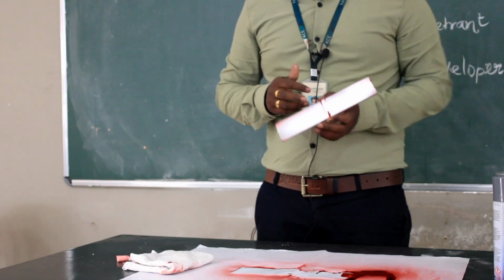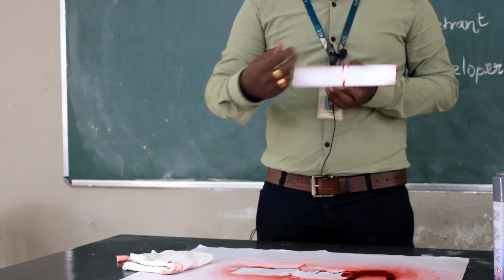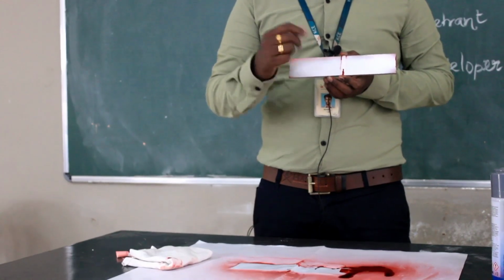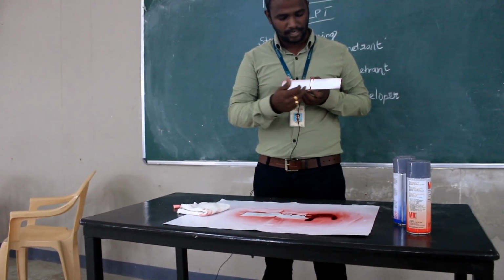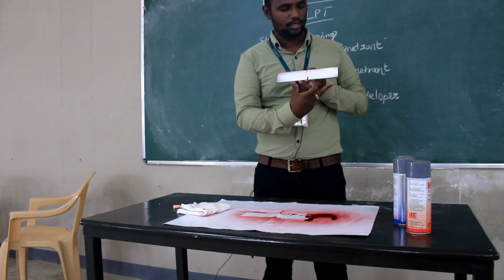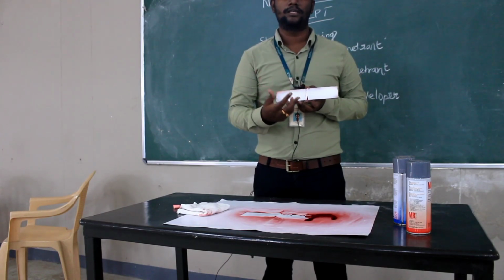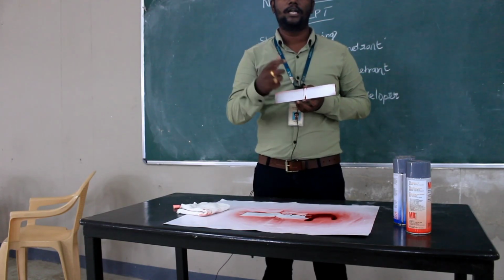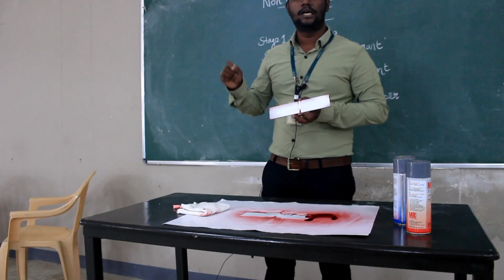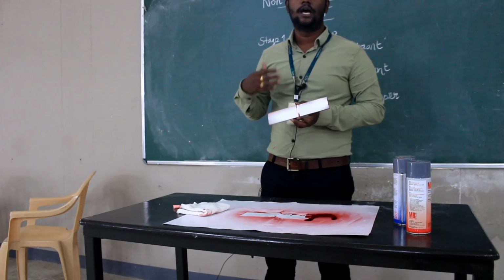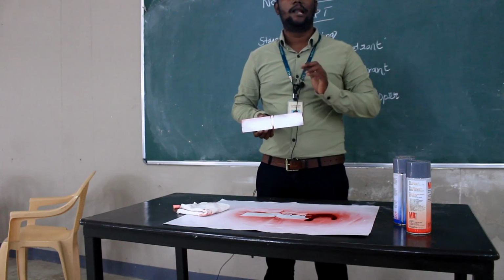The inspector will take a report so that he can note the defects observed in the cracks and mark where each crack is present. He has to mention the dimension of the crack, the location where it is present, and what type of crack is present in the welded sample. The inspector will record this in the report sheet, which will be given to the priority official for inspection. So this is what is called liquid penetrant testing.